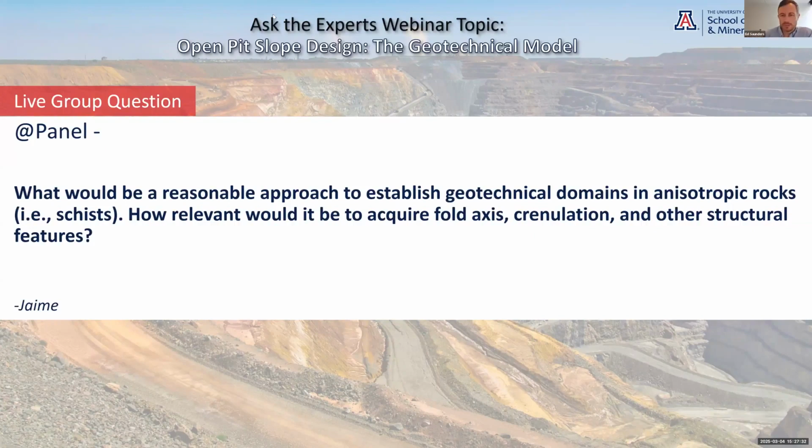Oh, I'll jump in, Gillian. Probably speaks to a point just earlier: don't make too much interpretation too early with your stereographic projections. This speaks to the complexity. Understand your major fault, your major joint or discontinuity patterns.